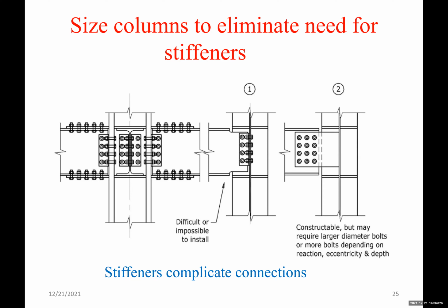We're using 3 columns of bolts with 4 rows. And of course, in this case, we have to design for the moment due to the larger eccentricity in the connection, and of course, distribute the load properly between the bolts and the welds, which also from a design standpoint would require an effort from the structural engineer or even the connection designer who's designing this. So this could be solved to a simpler connection by increasing the column size.